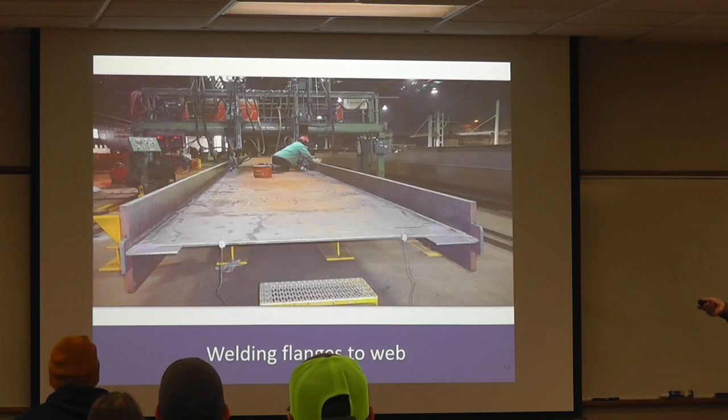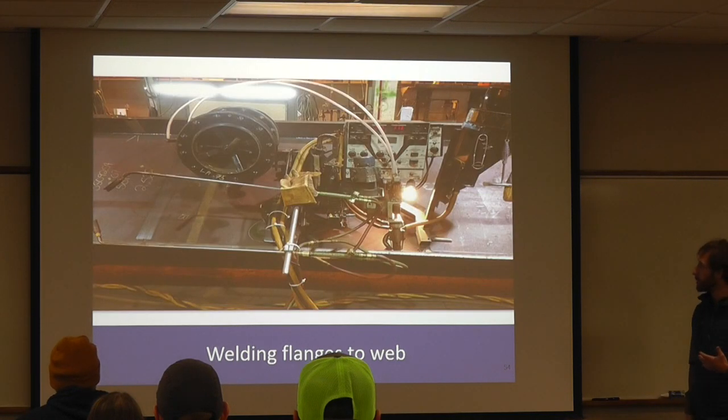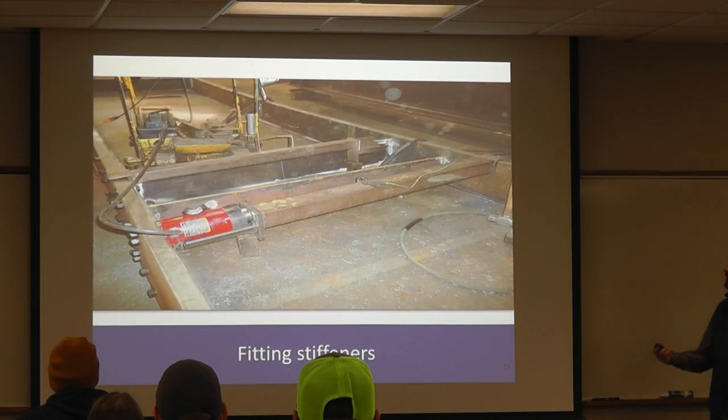Now you'll notice in this, we have those transverse stiffeners, right? None of those have been installed yet. And that's to allow for this automated welding process, so that you can have that weld traveler keep going along like the bead. So we'll go ahead, put that weld down, and then that's where we're going to start fitting the stiffeners.